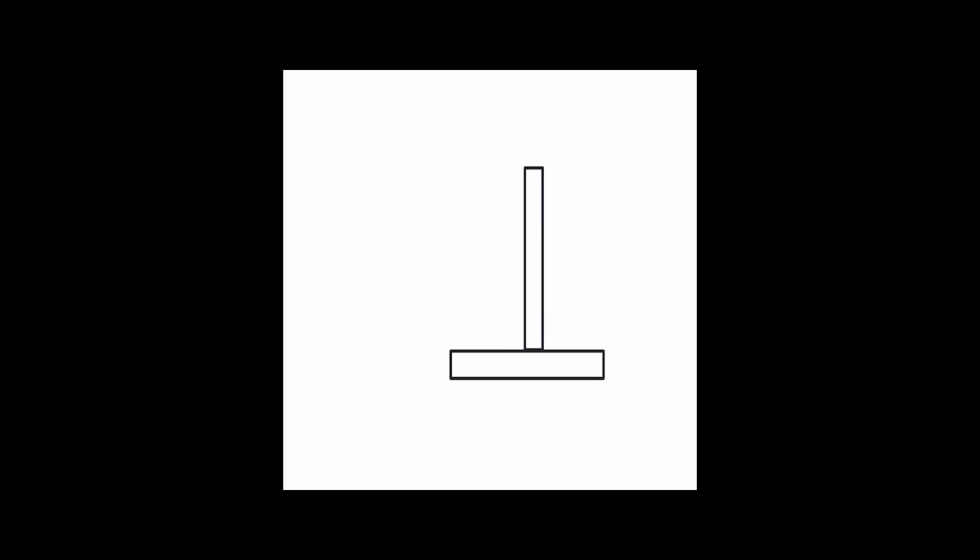All right, one more example. I'm going to stick with the T-joint, and let's say the reference line is now coming in from the opposite direction. So whereas before it was coming in from the right to the left, now it's coming from the left to the right. And let's say I give you a fillet weld symbol on the bottom side of the reference line. Does that change the side significance when it comes to arrow side and other side? What do you think? So when the reference line changes direction, the side significance actually stays the same.